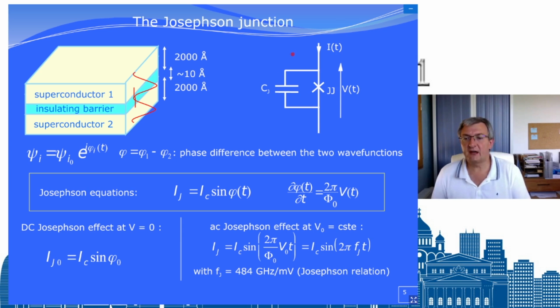If you see this junction, I talked mostly before about this part. It is a quantum current, a tunneling current. This tunneling current can be either Cooper pairs or quasi-particles. But as you see the device itself, obviously, for pure geometrical reasons, there is a capacitor. It's a very thin barrier, so there is a high capacitor, and it has some influence.